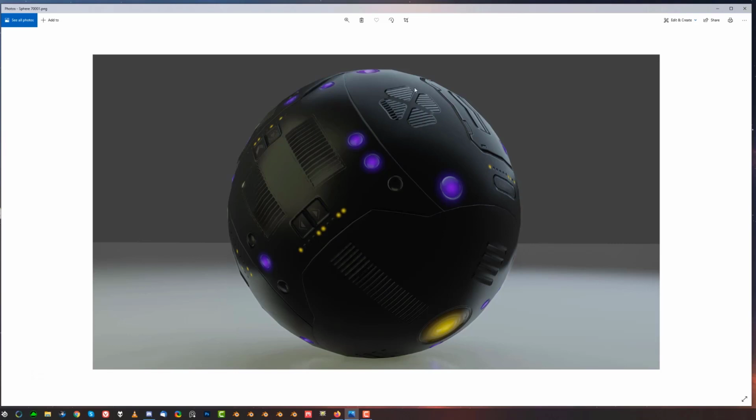And also when you render something, make sure that the sub D is on. Because it's a sphere, I'm guessing you just added the quad sphere from Hardops. Actually, it's not Hardops, it's Machine Tools. This sphere is not really that densely subdivided, so drop a Ctrl+2 and you will see this faceting on the decals disappear.